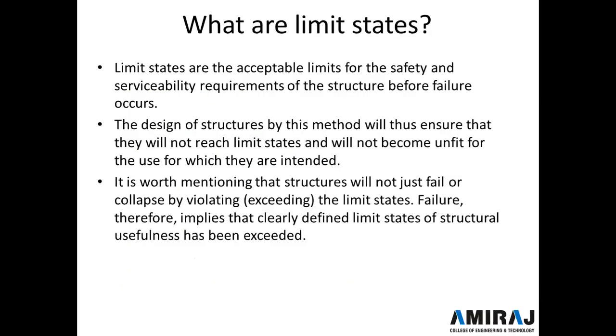Now going further, what are the limit states? The limit states are acceptable limits for the safety and serviceability requirements of the structure before actual failure occurs, right? So the design of structures by this method ensures that they will not reach limit states and will not become unfit for the use for which they are intended.